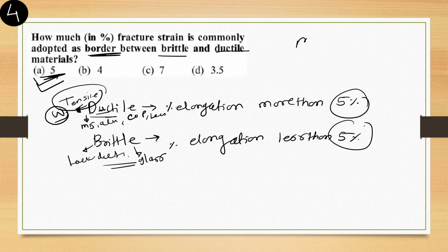In case of malleability, you can remember it as MS, malleability into sheet, and ductile as wire. Malleability is a property that can resist a compressive force. If you apply a compressive force on a malleable material, it converts into sheet. And if you apply a tensile force on a ductile material, it converts into wires. So option number first is correct for this question.